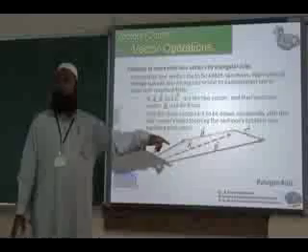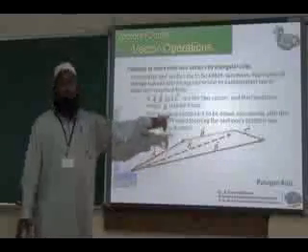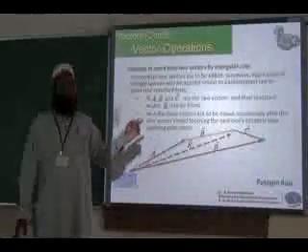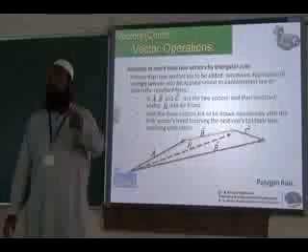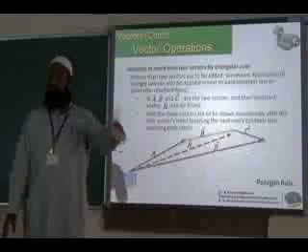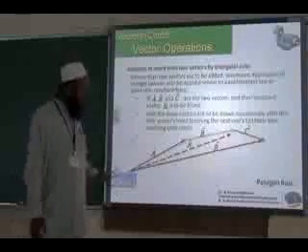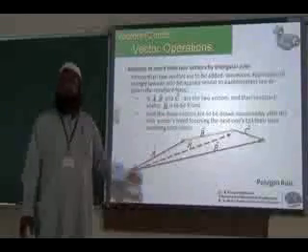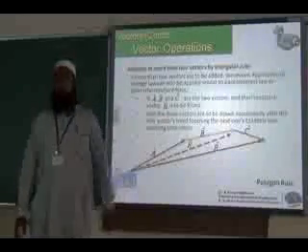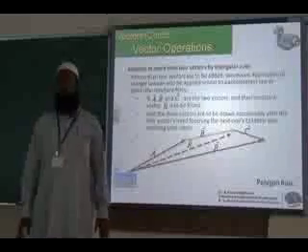Okay, so we can directly go for drawing A, B, C successively with each vector's tail touching the previous vector's head, like that, to the angle given, and join the starting point of the first vector and ending point of the last vector. That gives you the resultant.